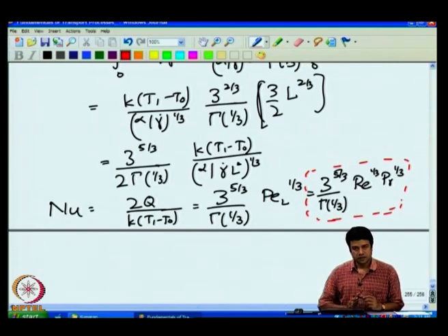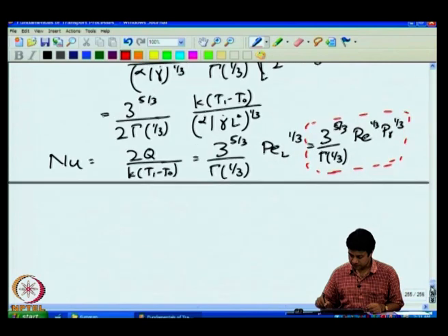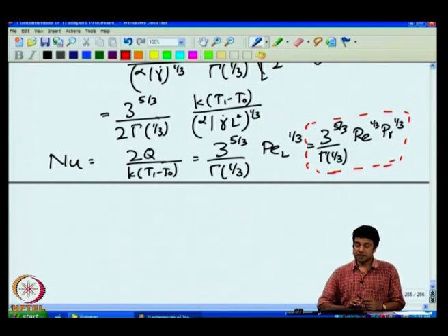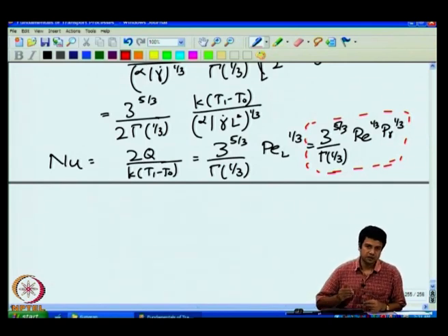In the limit where the flow is laminar, so that the velocity is linear at the surface, the correlation for heat transfer goes as a constant times Peclet number to the 1/3 power. The reason it goes as Peclet number to the 1/3 power is that the heat flux from the surface goes as the temperature difference divided by a length scale. That length scale goes as Pe to the power minus 1/3 from the scalings that we had just derived. Therefore, the Nusselt number will go as Pe to the power plus 1/3, as expected.